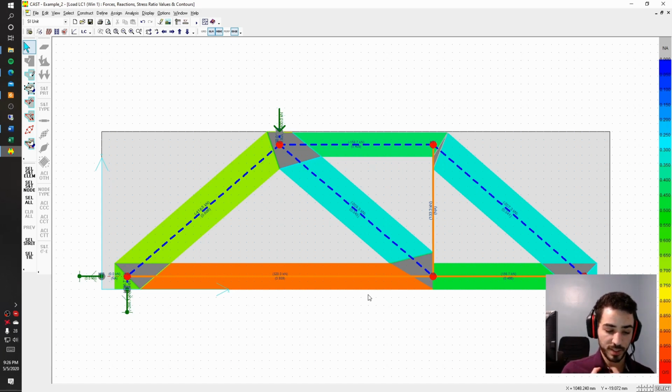That gives us 733 millimeters that we will use to bundle all of our vertical reinforcement. Vertical reinforcement, especially in beams, is usually two-legged. It can even be three-legged, but in this case let's consider it's two-legged. So we will consider one hoop as two areas of steel because we have 2 legs.